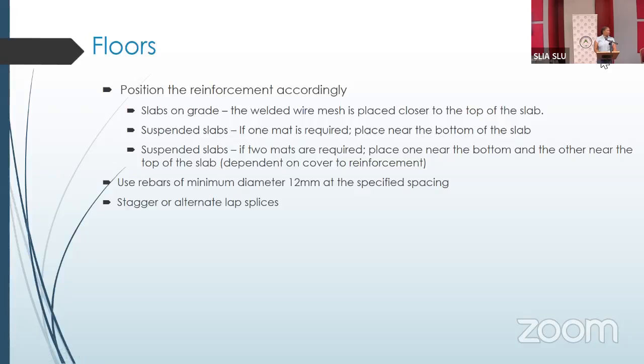You have the minimum diameter, which is specified. Again, as I said, it's a T12. And where we have splices, we alternate or we stagger them.